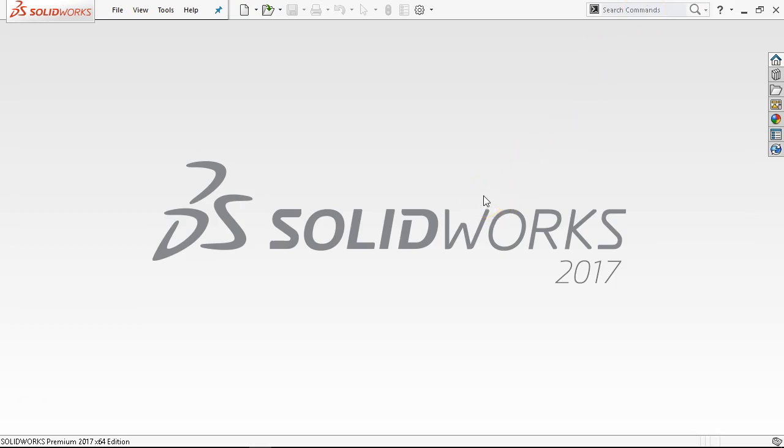So again, probably too many ways to go find something, but you have it available in front of you one way or the other. When you first launch, then we have the standard toolbar for the open, saves, prints, the all-important rebuild. And there are two rebuilds, and I believe it doesn't give me the hotkey, but I want to say it's Control-B, as in boy, is kind of a just go ahead and rebuild.